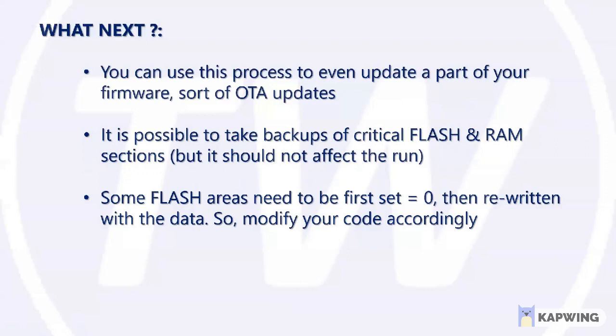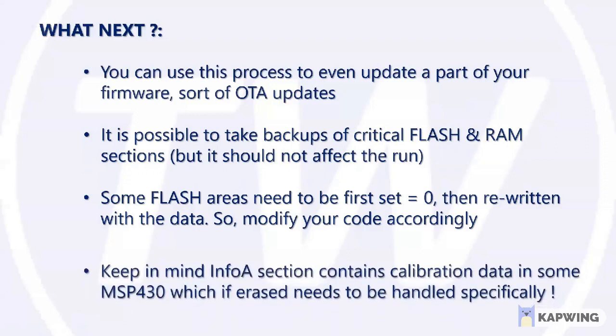That's up to you. If you don't want to set it to 0, if you don't want to modify the segment, you can go for that. And as I said, please keep in mind that there are some sections of your microcontroller, some flash areas, which contain calibration data.